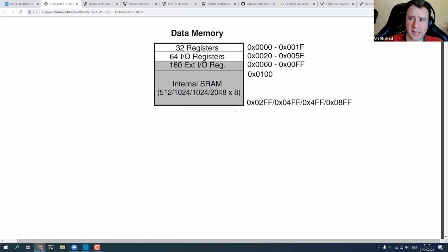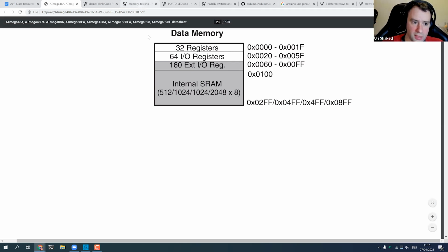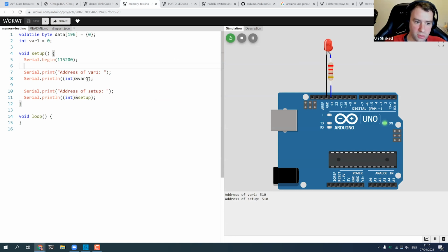So that was a quick overview of the memories that we have, the program memory and the data memory. I think the important takeaway is to remember that they are two distinct things. And when we are asking to read data, we should tell the microcontroller if we want to read from the data memory or from the program address space. When we write, it's pretty simple because we can only write to the data space and not to the program space.